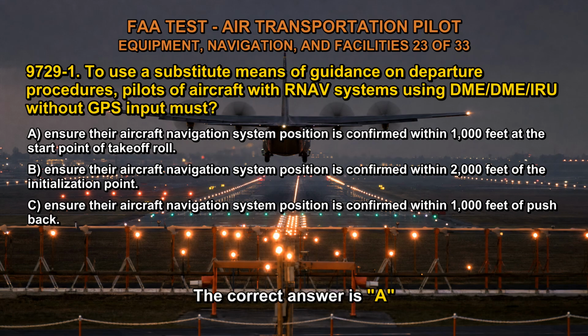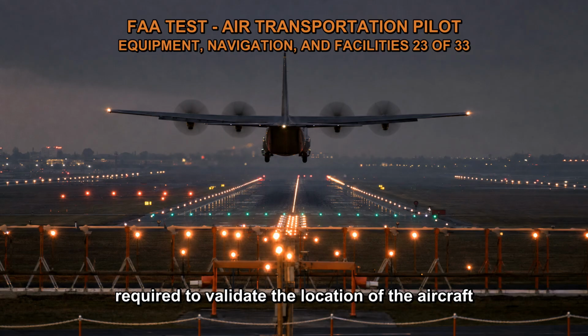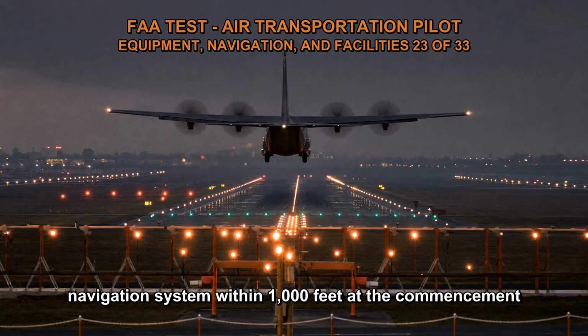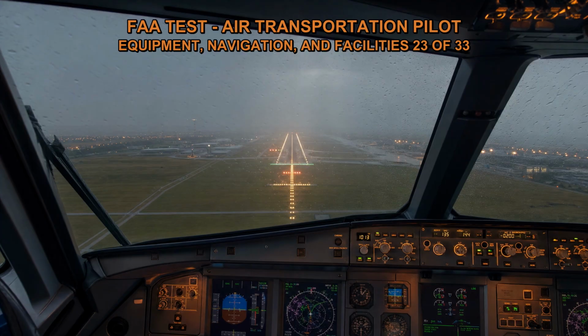The correct answer is A. Pilots of aircraft without GPS utilizing DME/DME/IRU are required to validate the location of the aircraft navigation system within 1,000 feet at the commencement of the takeoff roll in order to comply with RNAV-1 DPs and STARs.